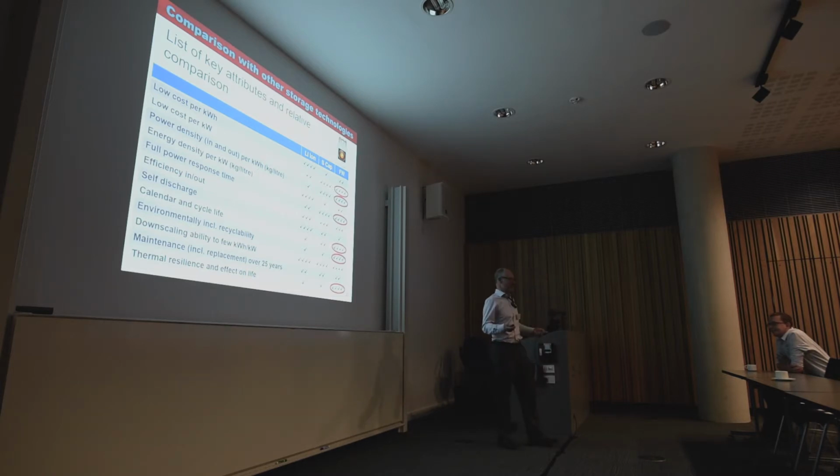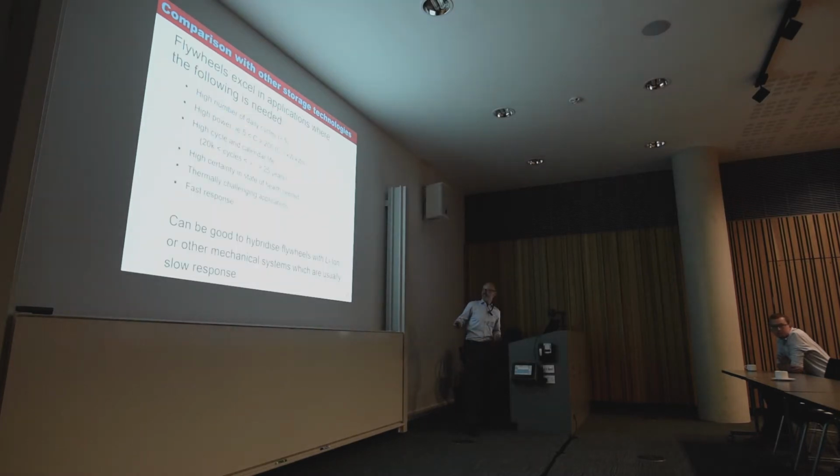And the fact of knowing your system: as long as the flywheel's spinning, the bearings haven't gone, it hasn't blown up, it's not degraded, it's working. So you just need to know the speed pickup, that's all you need, not a complex equation. So it really works well in this sort of high number of cycles, more than 5 a day. It's not every application, but certainly more than 5 a day.